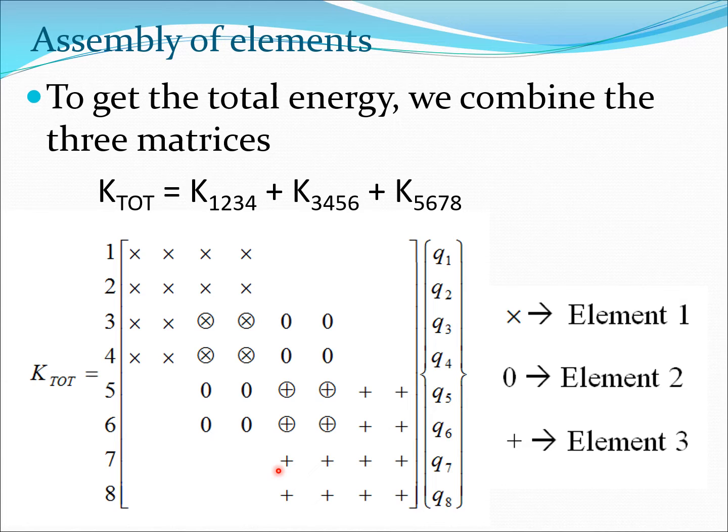Okay. So you can see now that the total stiffness matrix which we have obtained has 8 degrees of freedom corresponding to the complete beam, and as you would expect, this is the first part, this is the second segment, this is the third segment. Whichever parts you see, there is a mixing of the components from the element 1 and 2.